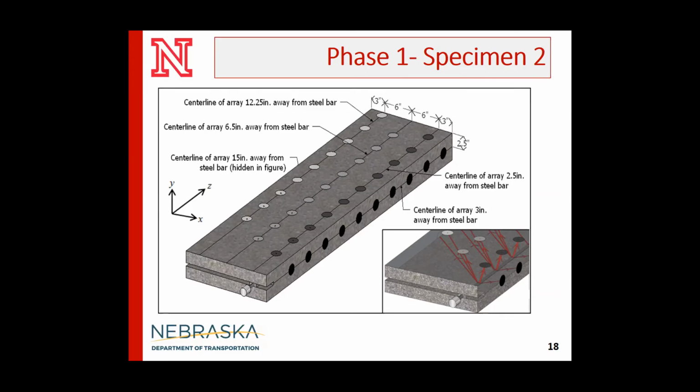You need to think about the different types of waves that go into it and how they travel within concrete and the angles they will have. So when you take a measurement at a spot, that doesn't mean the flaw is right under it. It'll probably be at an angle, so you have to back calculate where you're seeing that flaw.